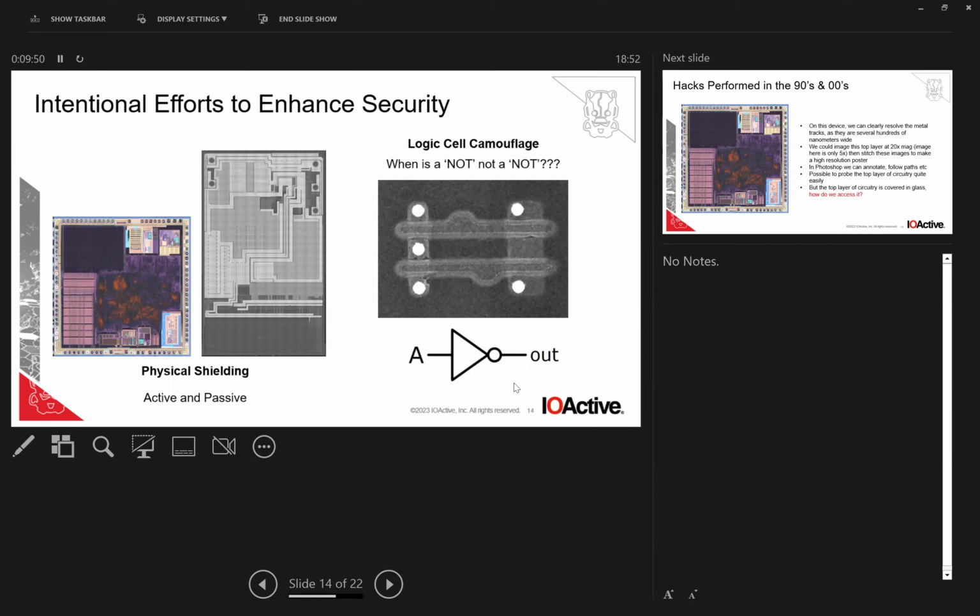It might not be. But imagine if you could actually just get a needle on this chip and touch the signals on the surface. That would be cool. But the chip is covered in glass, so you can't do that. Well, you can, but you have to use some chemicals. So as an example, this is what used to happen. Basically, you'd burn a hole in the package with nitric acid, just so you can get to the surface of the chip. You clean it.